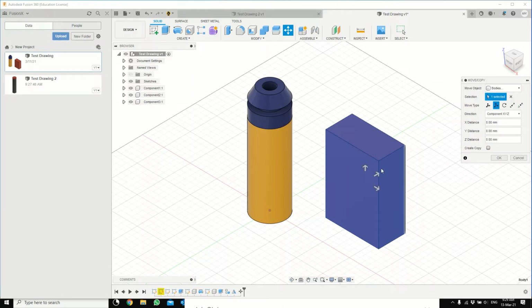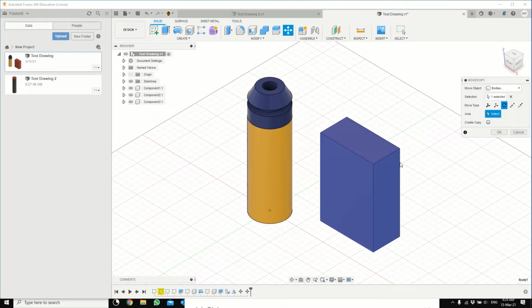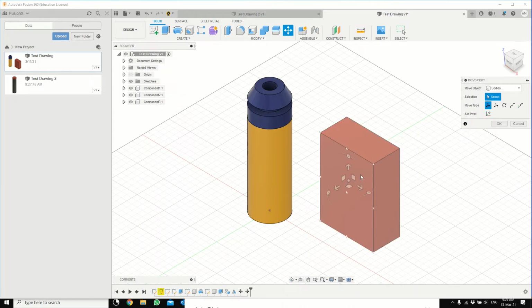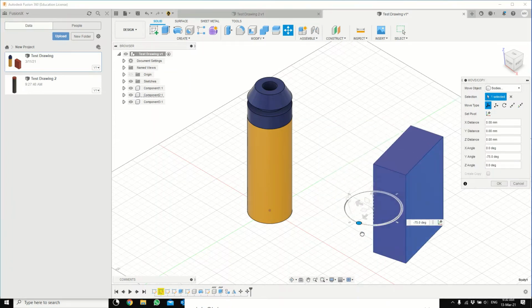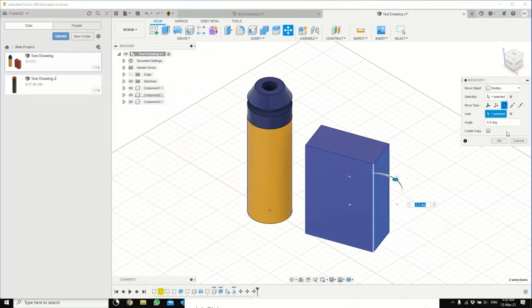If you want just translate, it will decrease the options you want. If you want to just rotate, you have to select the axis. Now, in the free move, before it was in the middle, now it's in the corner. So I prefer you delete whatever it selects for you and select yourself. Now in this case, you can select whatever edge you want to make the rotation on. And the same goes for the rotate function. You select the axis you want to rotate and start rotating around it.